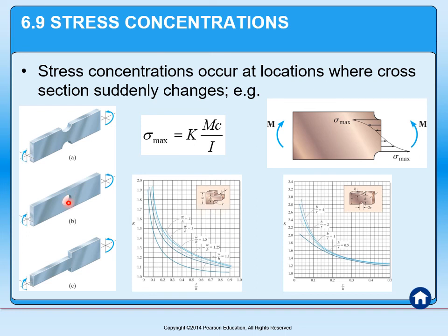Keep in mind, if you recall, the stress value is maximum at the surface. So the further out you go with these kinds of discontinuities, the more effective they are. So you'll notice in any kind of building technique, if you're going to drill a hole through a beam, for example for plumbing or electrical, they always want it in the middle or in the upper section where it's going to be under compression, so it actually closes that hole up.